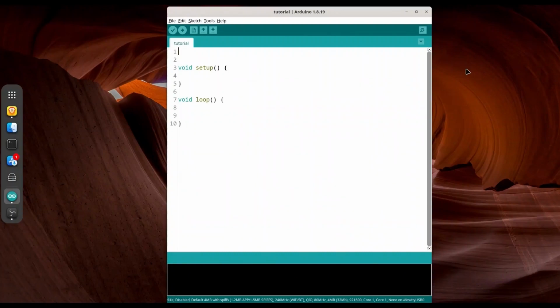But this is not going to be a simple task because we are not dealing with analog but with digital pins. So instead of using voltage to set color, we are going to use pulses. And how is that going to work? If, for example, we want our color to be 20% red, 20% blue and 20% green, that means that all 3 pins need to be turned on 20% of the time, equally spread through a time unit. So if we observe one time unit that contains 100 smaller time units, that means that we want our pins to be turned on in 20 of those 100 units. But of course evenly spread in order to get the best effect.